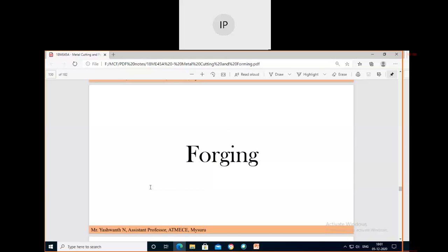Also mentioned here is one more important term, recrystallization temperature. In the material science subject, you studied the crystalline structures, microstructures and different lattices of materials, such as BCC, HCP or simple cubic. Inside we have the atomic formations. Once I heat the material, there are changes in the atomic formation, the granular or crystal structure. Changes in this granular structure are called recrystallization. Once the working temperature is above the recrystallization temperature, we call that hot working, and if it is below, cold working.